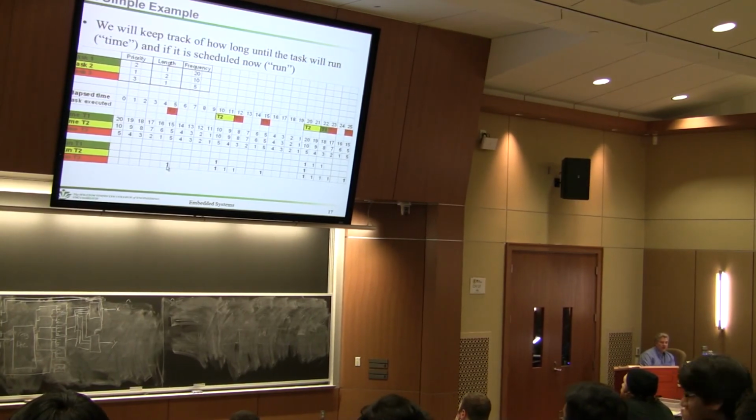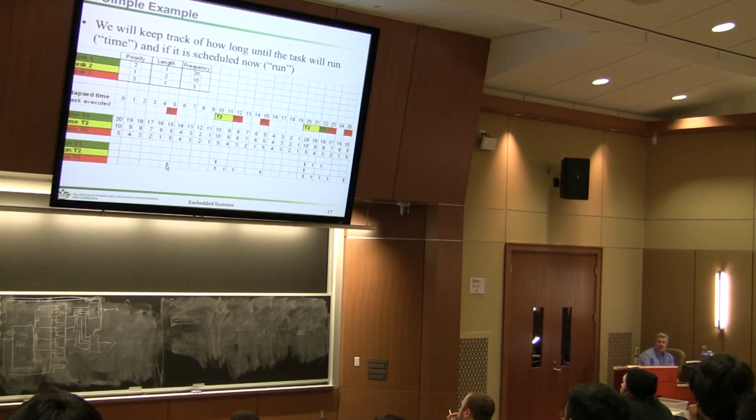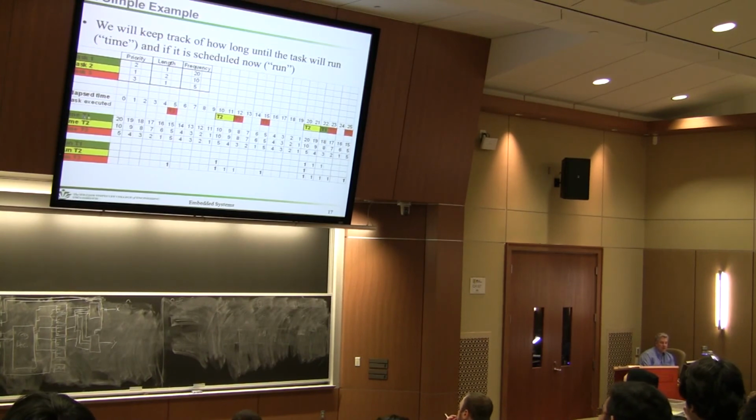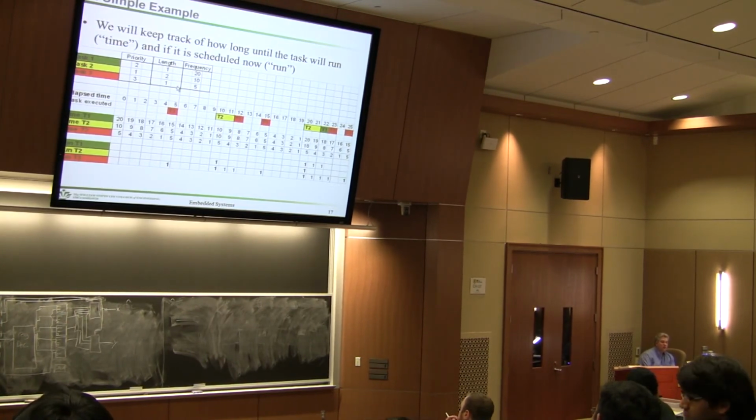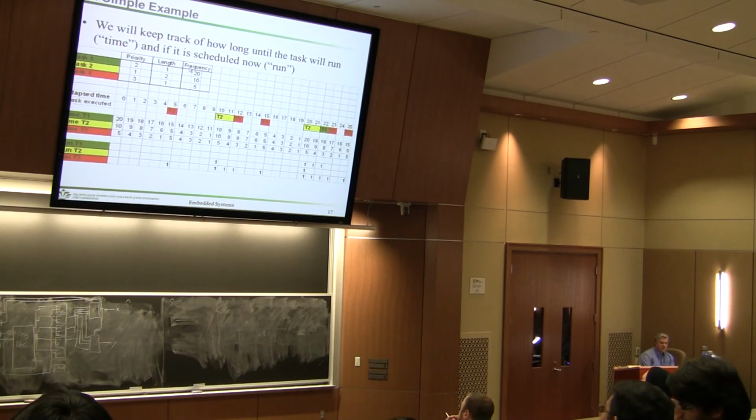And in fact, in this case, I make it bold if the variable run has been set during that time frame. Then you have another variable which is called time, which is a running counter as to how many timer ticks will occur until you count down from 1 to 0. And then there is a stored variable here called frequency, and that tells you what this value right here in time is going to be reset to every time that you count down from 1 to 0.